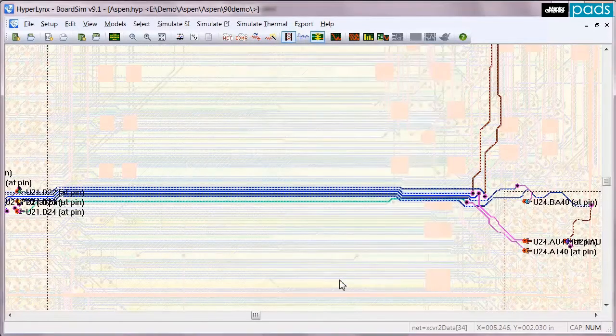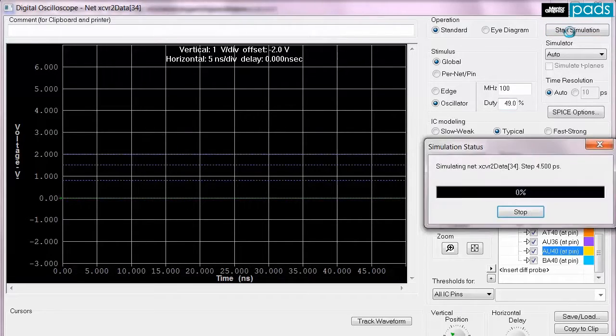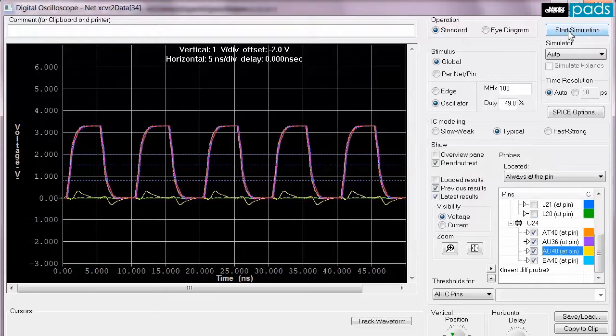simple geometrical checks. After running the crosstalk simulation on the selected net, it is clear that there is a significant amount of crosstalk present, and zooming into the far end of the crosstalk waveform, you can see that the level is sitting at around 300 mV.